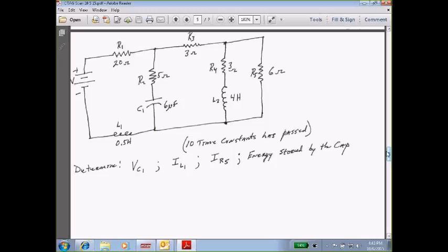And after 5 time constants, it's 99.99% charged, so we consider it to be fully charged. And then for an inductor, it's L over R, and for a capacitor, it's R times C. That's how you find the time constants. Now, if it's in a loop and there's more than one resistor, then it's your total resistance and your total capacitance.